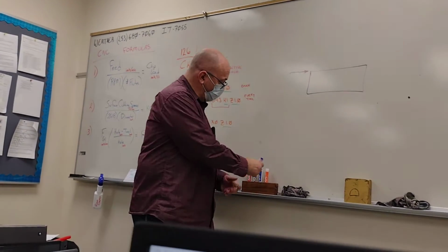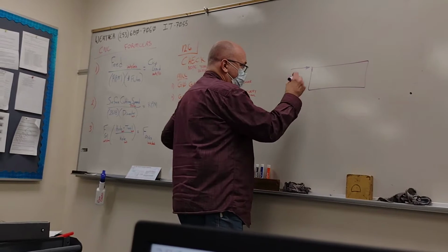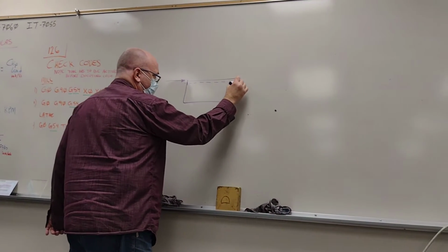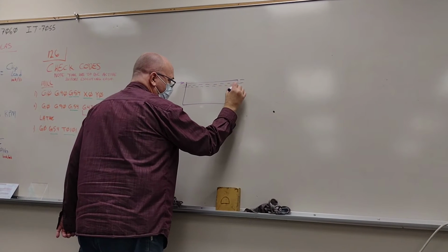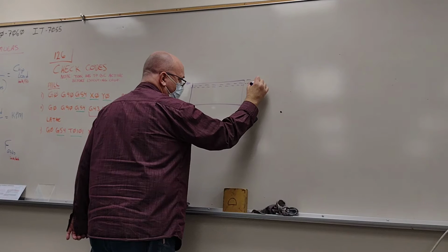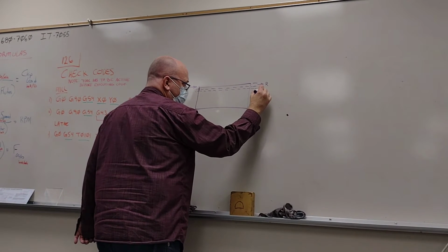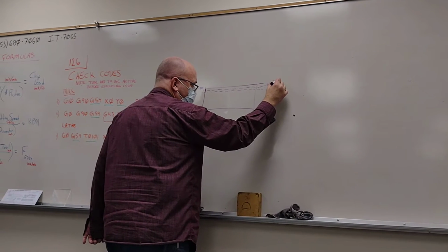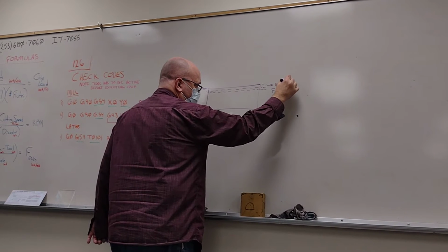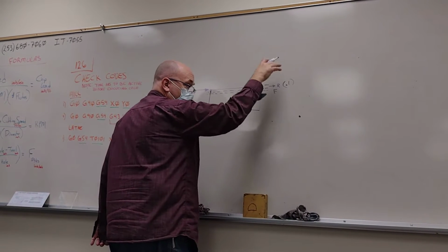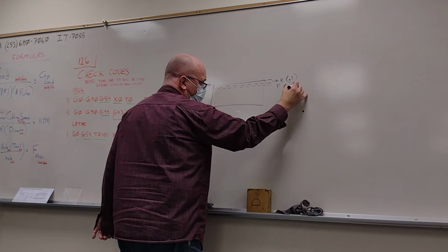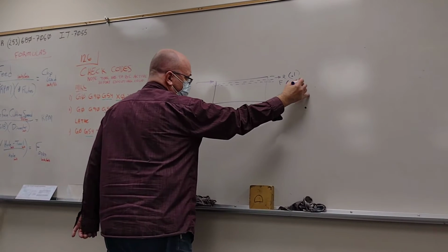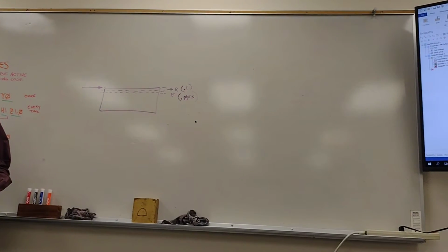One tool path to rough it, and a second tool path to finish it. So one way you would do that is the first tool path would come through here and take most of it off, and the second tool path would come through and take a little bit less and finish. So this might take off maybe 100 or more. Maybe you've got a lot of material. And the finish pass, maybe 10 thousandths, 5 thousandths or something. Finish pass. You might even have a rough, semi-finish and finish.